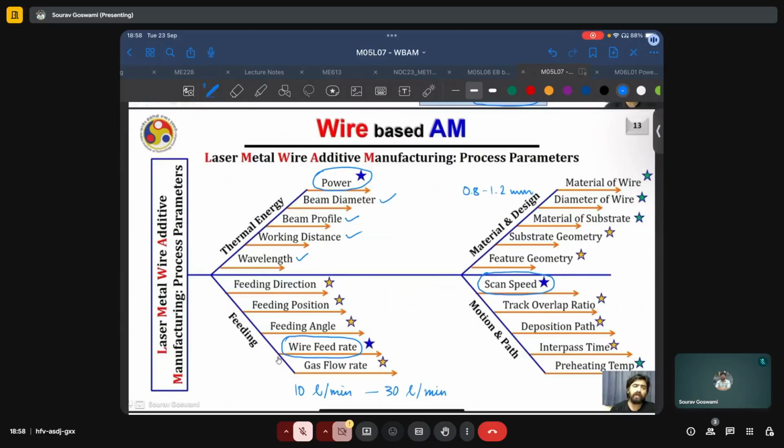An interesting variable which you see here is the preheating temperature. This can prove especially useful because when we are depositing any molten material, typically it will be at some superheat, or in the critical case, we can assume that at least it will be at the liquidus temperature.